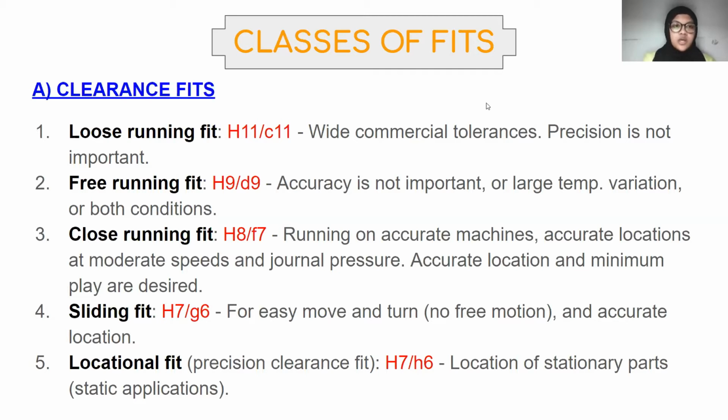Loose running fit is used for wide commercial tolerance. Precision is not important, and the code for this fit is H11C11.